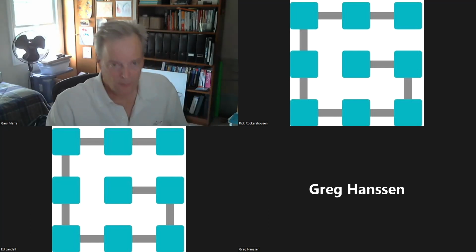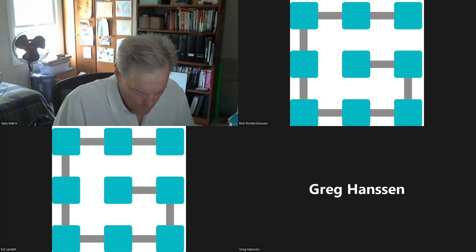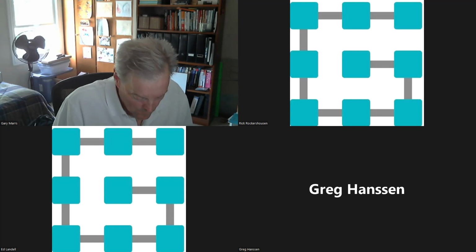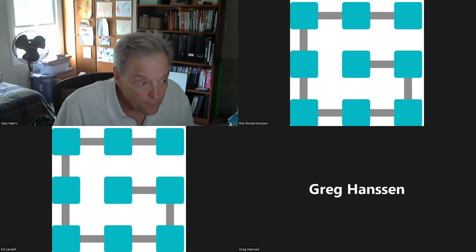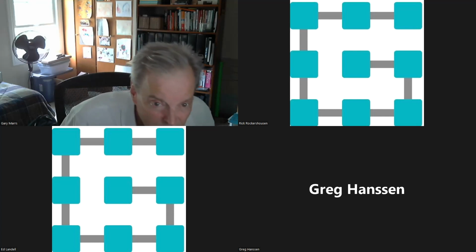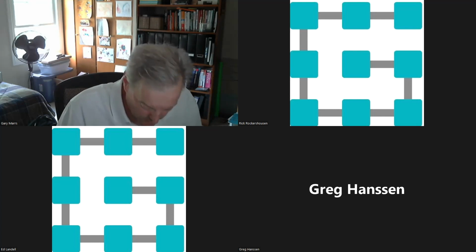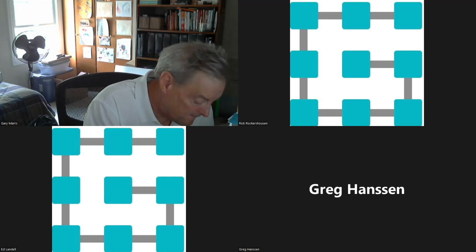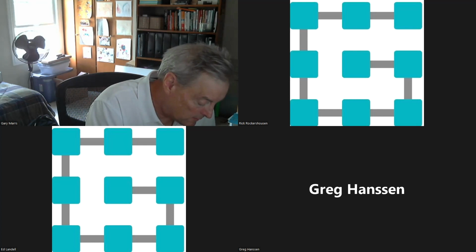Okay, so someone is asking Felipe, is there a simple way to filter messages using PCAN-View, other than using the trace function and manually analyzing it? I'm not sure. Filter bytes and bits from each message. There was a follow-on from Felipe. So I think what you're saying can be accomplished with PCAN-Explorer 6. You can filter messages. You can create symbol files to look at particular bits and bytes of each message.